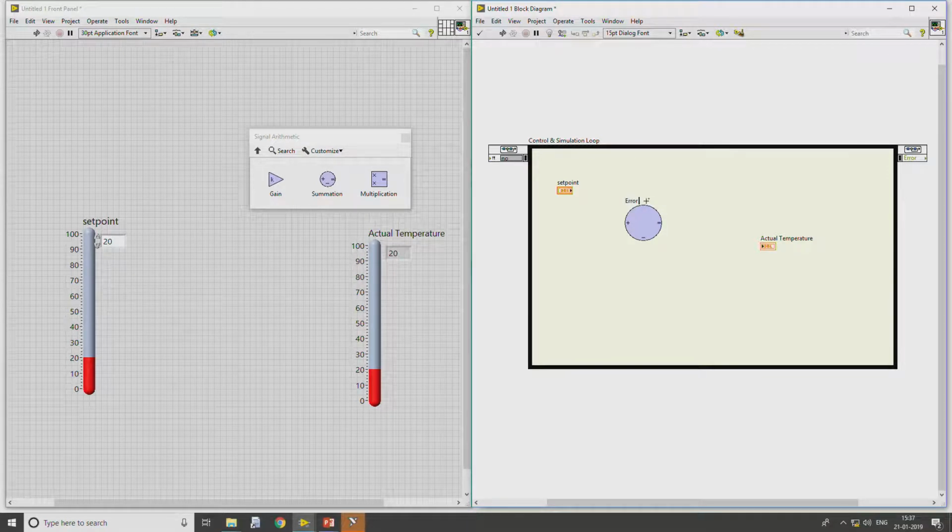So, not to confuse, I will change it to error amplifier or error detector. One input to this error detector is connected to the set point and the other input, the negative terminal, should be from the sensor, but in this case the sensor is externally connected.